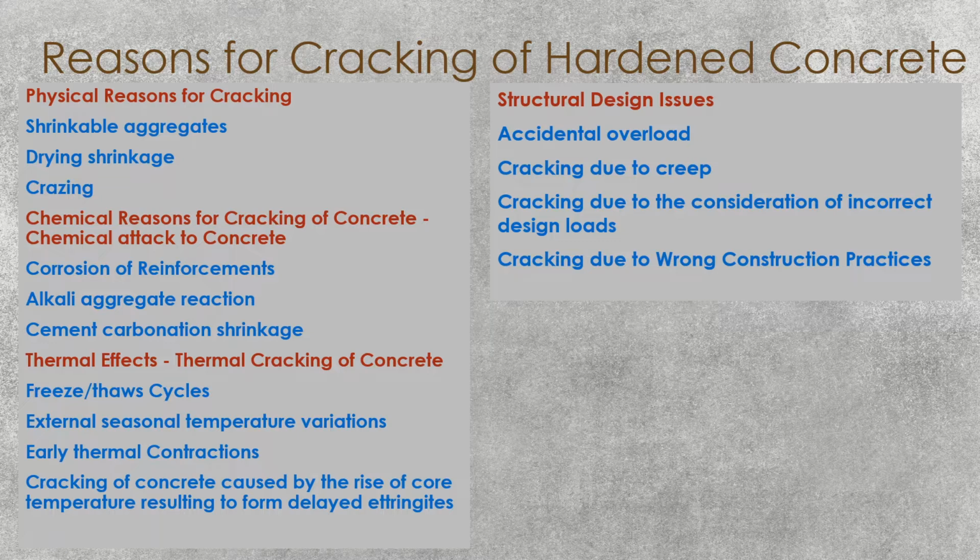Physical reasons for cracking of concrete: shrinkable aggregate, as some aggregates have shrinkage. Drying shrinkage in the concrete, which is also connected with the moisture movement of the concrete. Crazing is also one of the reasons for the cracking of the concrete.